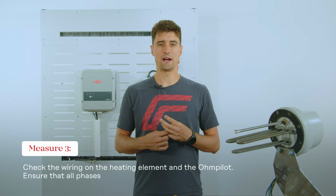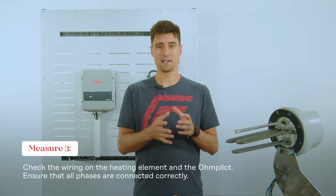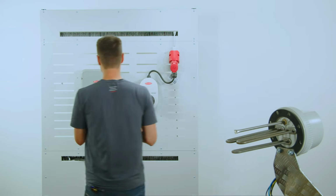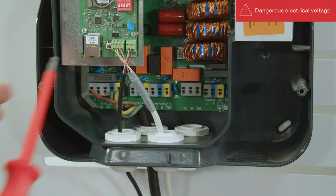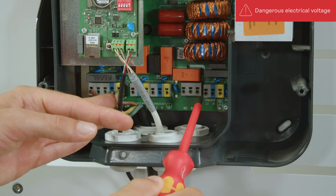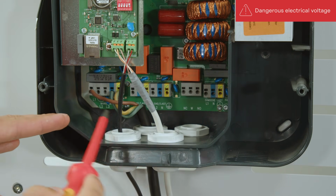Thirdly, please check the wiring of the Ohmpilot and of the heating element. It sounds very simple, but with the cabling, always mistakes occur. In order to check the Ohmpilot, I open the cover. On the left, you see AC input, and here on the right, this is AC output. This is where sometimes mistakes happen. AC output you see here is from right to left, L1, L2 and L3.